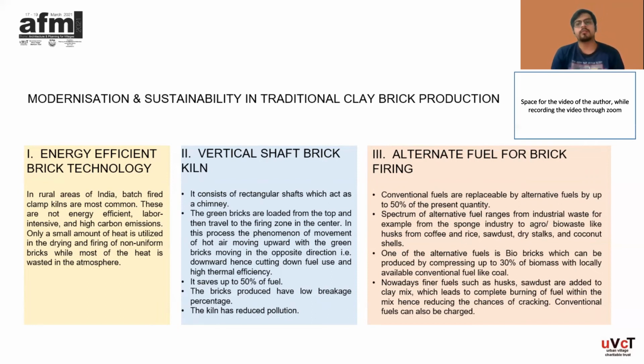One of the alternative fuels is biobricks, which can be produced by compressing up to 30% of biomass with locally available conventional fuel like coal. Nowadays, finer fuels such as husks and sawdust are added to the clay mix, which leads to complete burning of fuel within the mix, hence reducing the chance of cracking. Conventional fuels can also be charged. Let's move to the next slide.